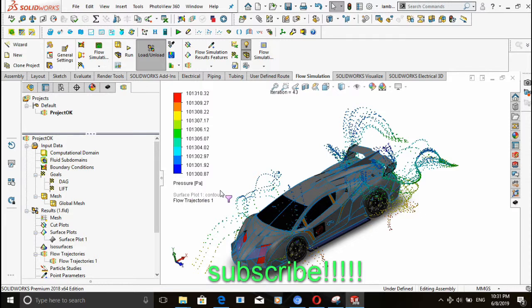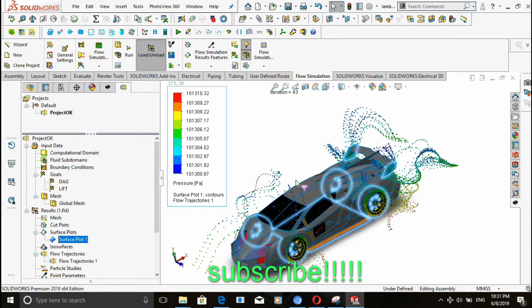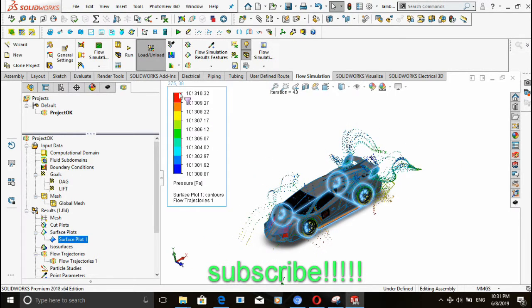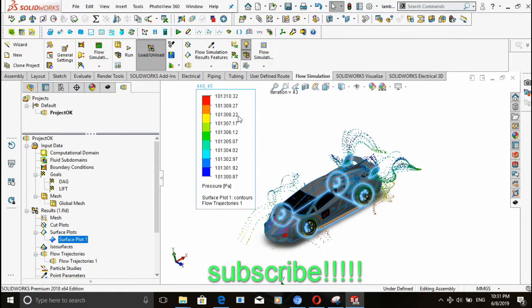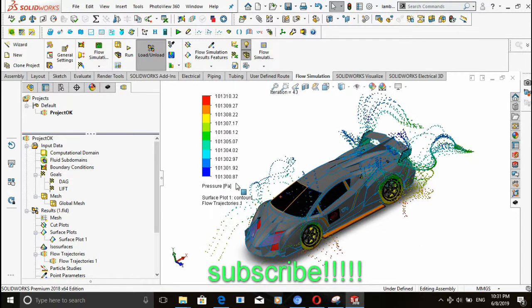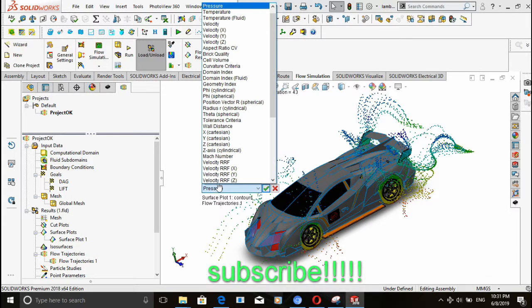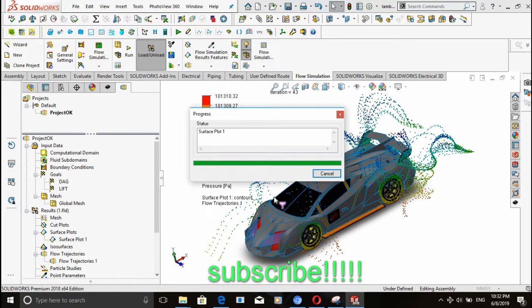So what I'm going to do is I'm going to bring in this show. So what I've done is this. So if you observe, we have brought in the surface plot, but at this level we can change the parameters. So you just come here, instead of pressure, we could decide to take the velocity following the x-axis and see how it's going to look like. So if I choose this, this is how it's going to look like.